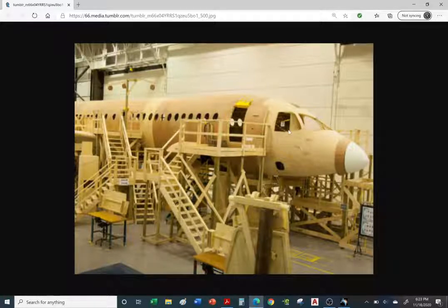And you also want enough room to be able to turn a wrench. When there's installation going on, sometimes you need room to install rivets or bolts and nuts, and you're going to need wrenches. And then sometimes there'll be some tight spaces where you have to get a wrench in to tighten a bolt or a nut, for example. Okay, so it's always a good idea to come up with a mock-up and not find issues later on when you're actually doing the actual assembly at the assembly plant.